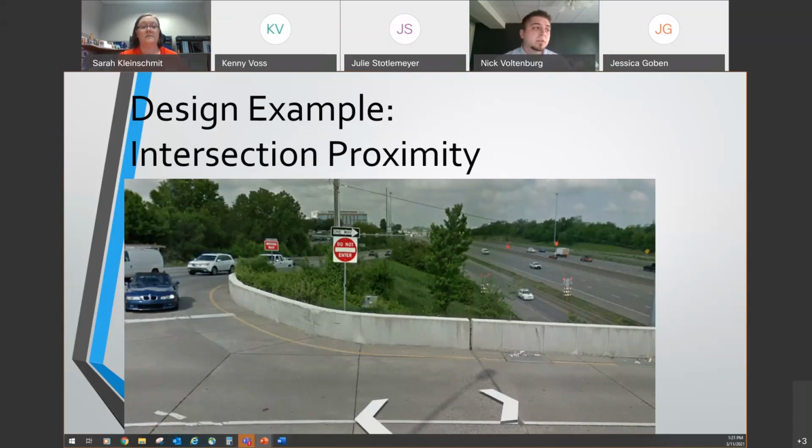One thing that we're always going to want to keep in mind, especially at intersections as you can see here, is that we don't want to create sight distance problems at this intersection. So if that is actually occurring, you may just want to go ahead and consider the block and height transition option instead, because we don't want to block off the view for our drivers.